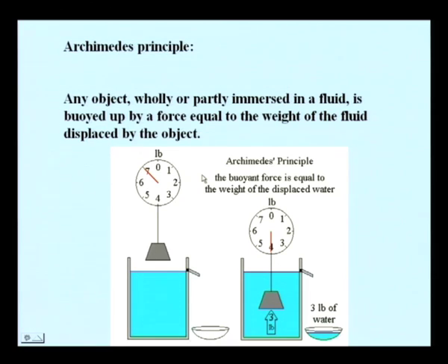The principle itself states that when a body is immersed in water, in a liquid, it will experience an upward force, and the magnitude of that force is equal to the weight of the liquid displaced. So, when the body is immersed, it displaces some liquid. The volume of the liquid displaced will be equal to the volume of the solid immersed. The part of the body immersed has a particular volume.